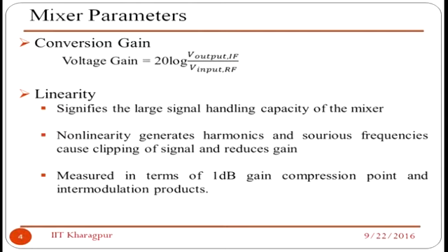If you make a mixer design, then immediately before you go to your conversion gain, you go to your FFT and find out whether your omega LO minus omega RF is coming as a strong band or not. If it comes with spurs, you know that we call them spurs, then it is not a very good mixer design. And I will show you some tricks to remove those spurs to make the fundamentals much stronger and isolated from the other harmonics.